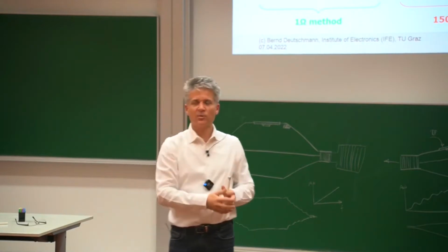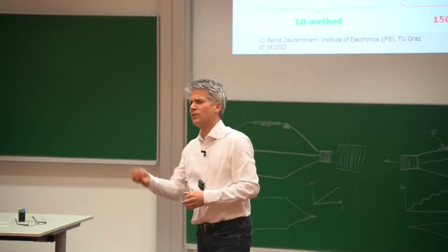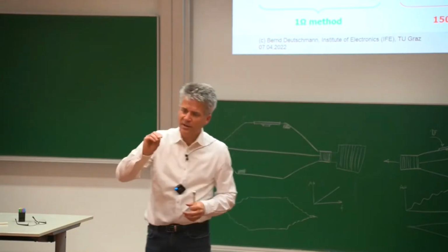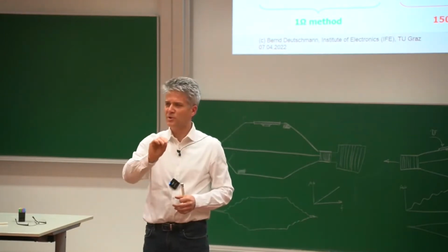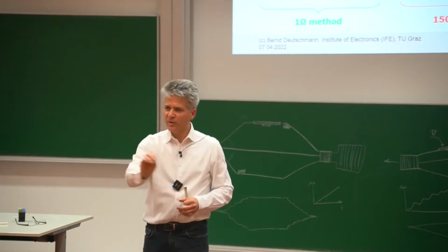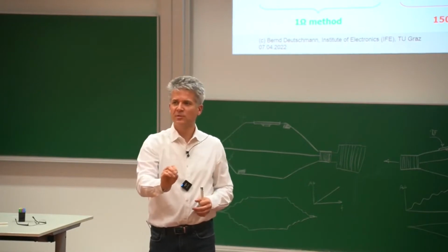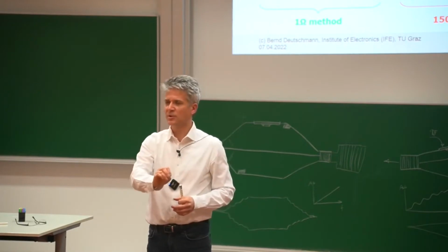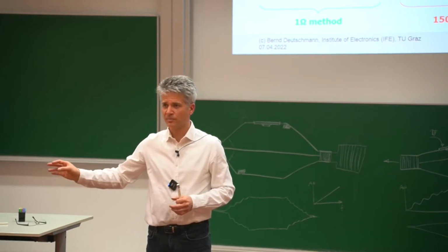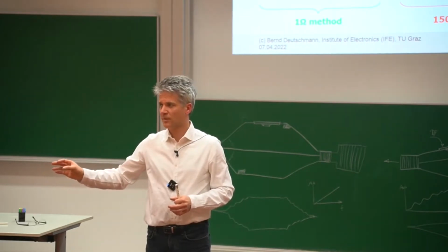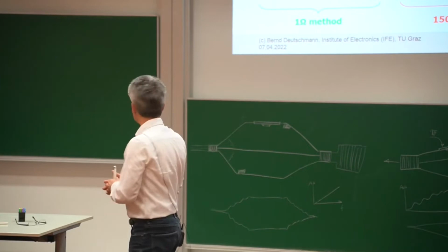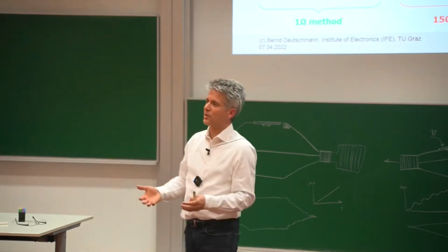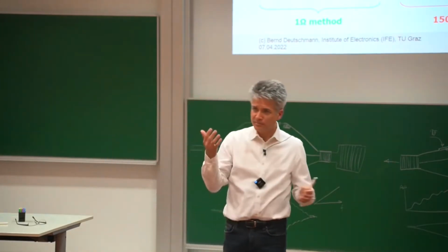So their idea was, hey, what if we are not connecting a cable to the pin, we are just connecting an equivalent impedance that represents exactly the same antenna impedance as the cable. Okay, then they made quite a lot of investigations. How big is the typical antenna impedance of a cable?